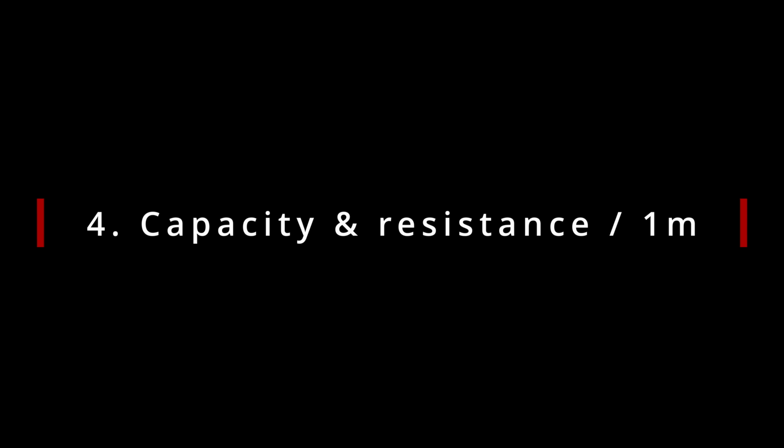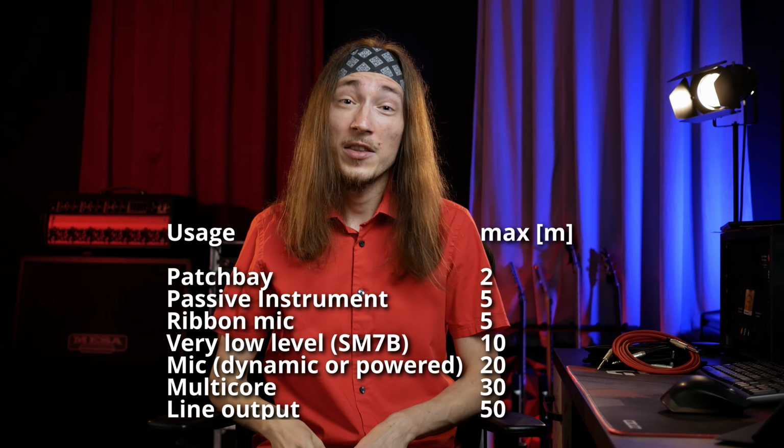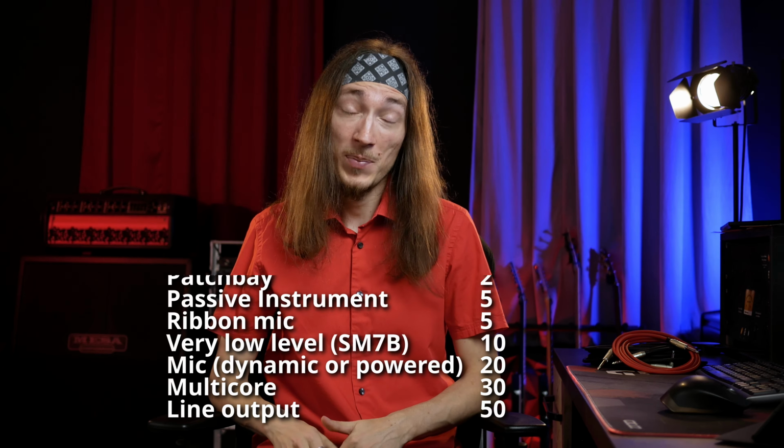Fourth, the capacity and resistance per meter. The final decision should be made based on the capacity per meter and the conductor cross-section, in other words, resistance. The more cross-section, the less resistance. It depends how long the cable should be and what devices should be connected with them. So if your cables need to be longer, you should probably get the better ones. But that's obviously more expensive. But if you want only short cables, you can stick with the cheaper ones.